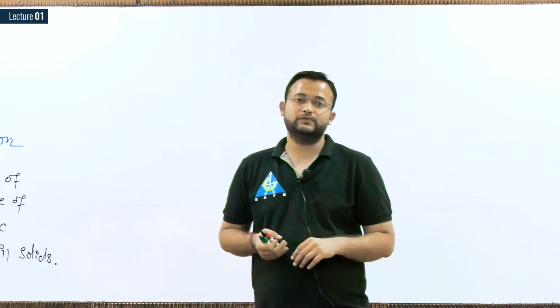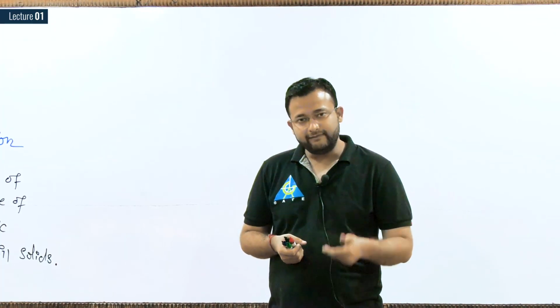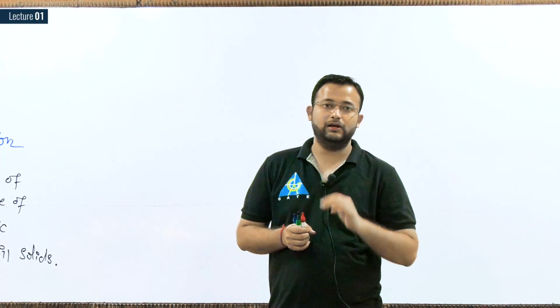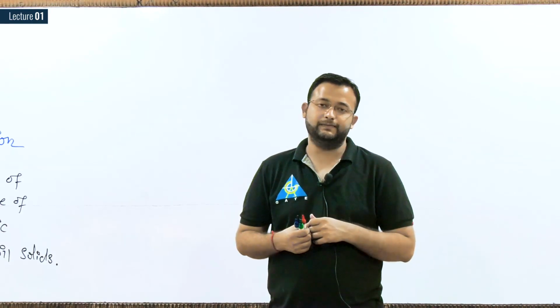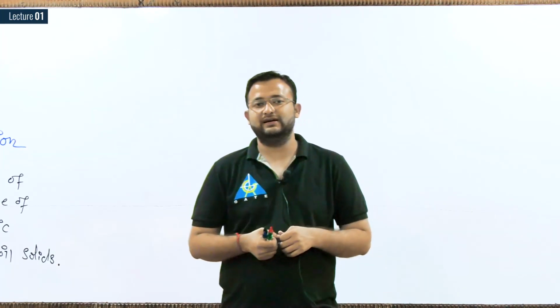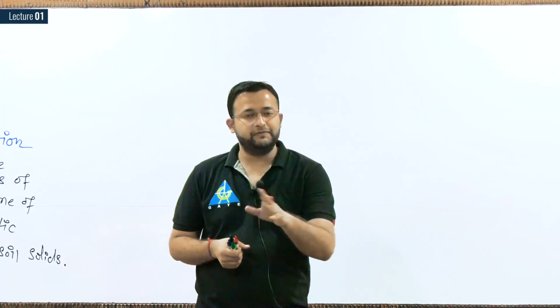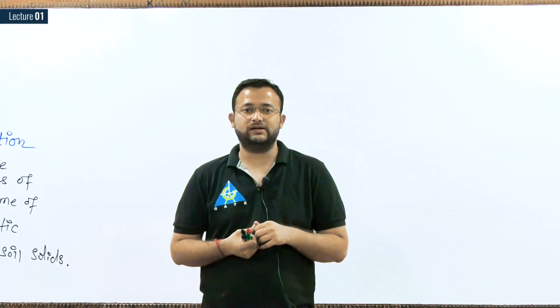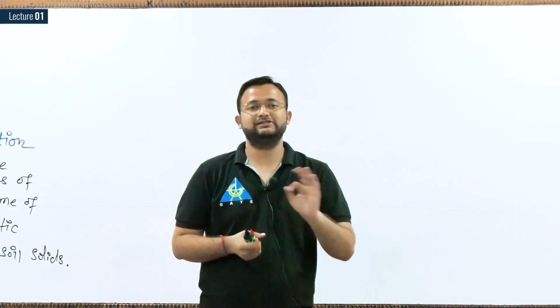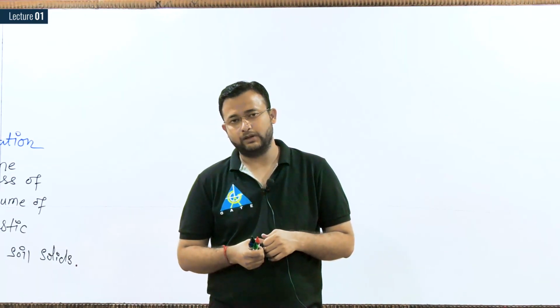Now the question comes, which process is possible? So I will tell you, compaction is possible before the construction of the building. Sometimes consolidation is also possible, some techniques are there in the market, but what I suggest, before the construction of any structure, any building, compaction is possible, and we do the compaction of the soil.